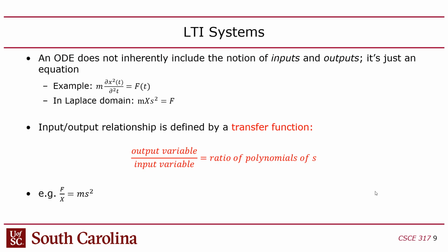And then the input, whatever it is, like voltage, I want to increase the voltage so the thing goes faster and imparts more force, that would be in the denominator, right? So what this boils down to is algebra. You just rearrange the equation using basic algebra to get the output variables on the top and the input variables on the bottom. That's it, right? Now, once you have that, you have a transfer function.